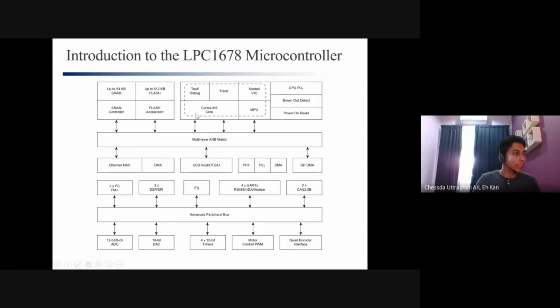So here we can see this is the Cortex-M3 core. So this is the CPU, the core of the microcontroller, right? So the registers that we learned, R0 to R15 in the programming model, are inside this Cortex-M3 core, alright? So the assembly language that we learn is also running inside here. All right. So here is the memory connected using this bus, and you will have other peripherals as well.